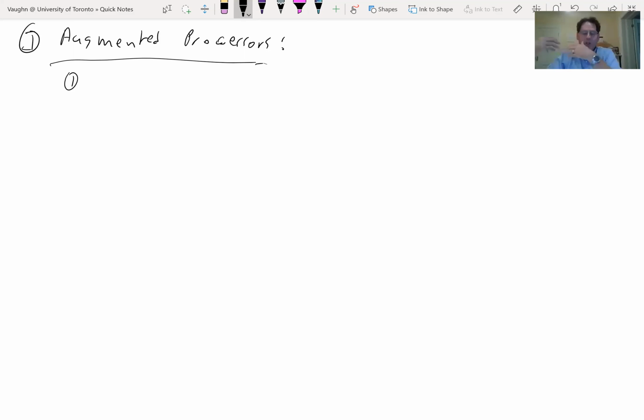What are ways that we can make a processor faster for certain computations? Expand, okay, yeah. So I see expand the instruction set. A good idea from Camilo. And that's usually given the name custom instructions. So we're going to put some extra instructions in that maybe aren't super generally useful, but they're useful to the exact computation that you want to do. Okay, so let me draw what this looks like.